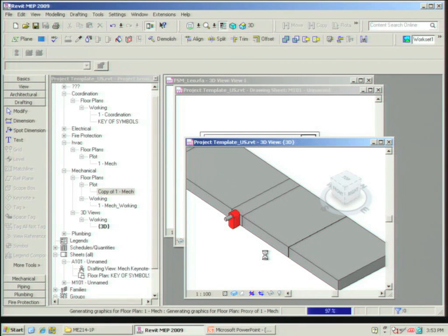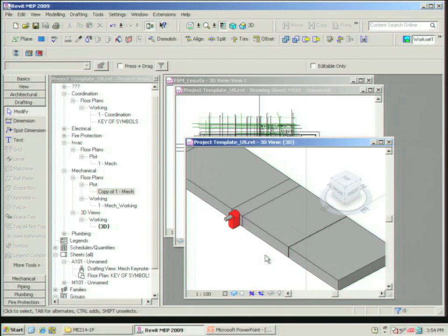By default setting, even in electrical views, you are using the mechanical discipline to show the architectural model as a gray line and our stuff as a dark line. But you want that mechanical equipment to be shown as a gray line, just like in architectural drawings, right? What I would do is create another filter and apply it only to the mechanical equipment on those electrical drawings. And in a filter, you can control that gray line style.